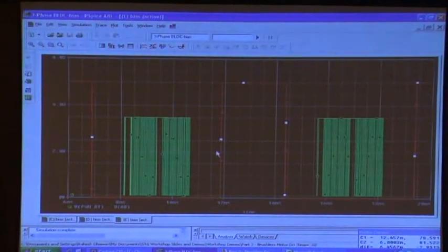Now, there's a difference in level. This guy is almost 3.5 volts, and this guy is 5 volts. And the difference is because we're using that AND gate, which internally limits the output to 3.5 volts. That's why it's actually good to eliminate that AND gate altogether. But it doesn't matter for the system performance.